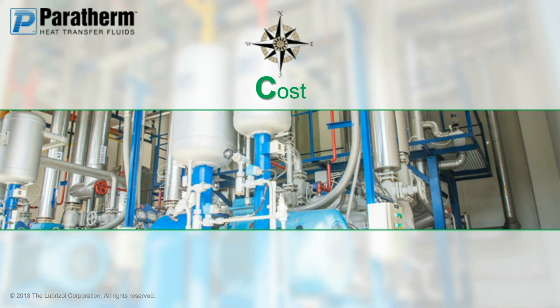And what do we mean by process control? Process control is going to take into consideration that you're going to need to make some kind of a modification to your system. Side stream filtration, inert gas blanketing on the expansion tank. So let's take a real quick example of that. You have oxidation concerns, and the last fluid you had gave you a lot of oxidation problems, created sludge. There's a lot of degradation based off of that. So you choose to move forward and find something that offers you the best oxidation protection you can find in your fluid.